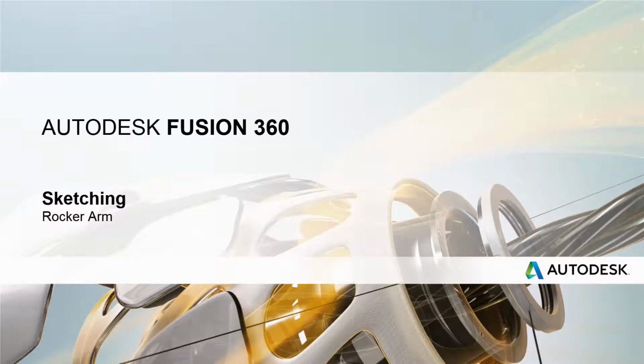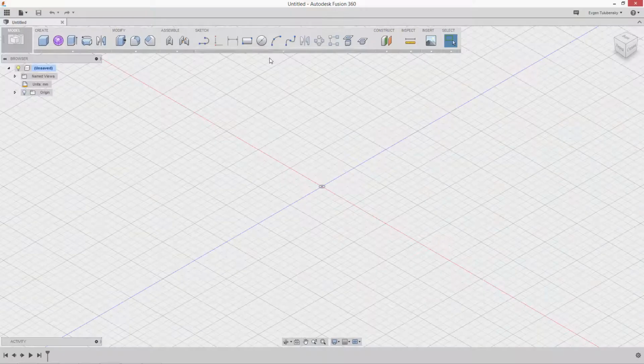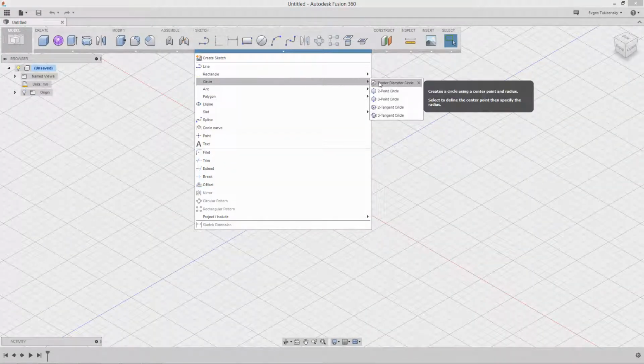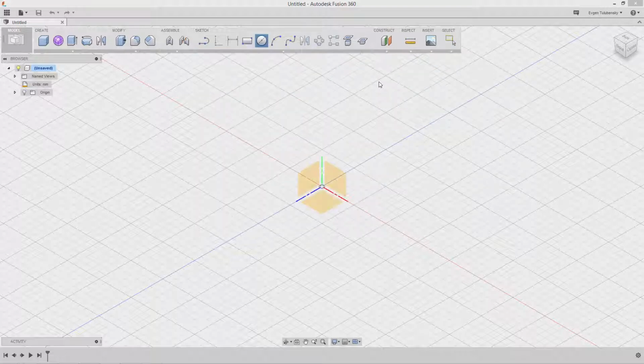Many features that you create in Fusion 360 start with a 2D sketch. In order to create intelligent and predictable designs, a good understanding of how to create sketches and how to apply dimensions and geometric constraints is required. Fusion does support 3D sketches, although in this module we will help you to learn the sketching tools to create and edit a 2D sketch. Now, we will begin to create some real sketch geometry that will be used to create 3D geometry.